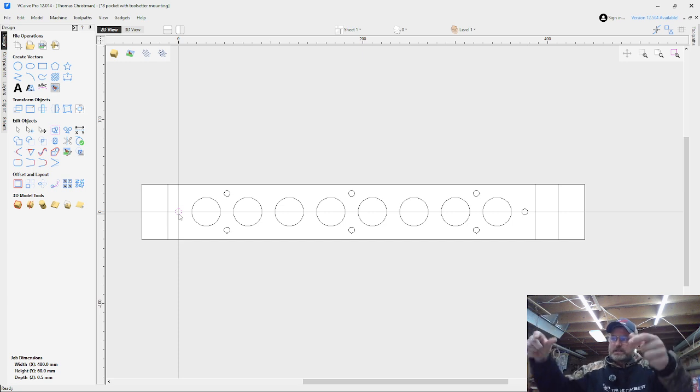That's how you put these pins in your ATC, and it draws these holes, and you put it down on your spoil board or on the base structure of your table, and that will position this perfectly on either the x-axis or the y-axis, so you get a perfect straight line. I highly recommend you do that.